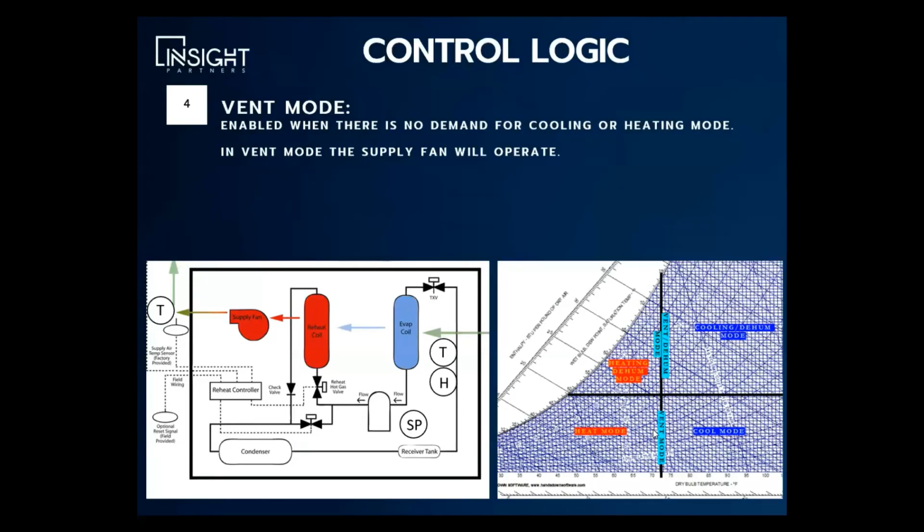The vent mode is our Goldilocks scenario, where the air is between the heating mode enable set point and the cooling mode enable set point. The air is already perfectly neutral and ready to be delivered to the space. No mechanical cooling or heating is required.